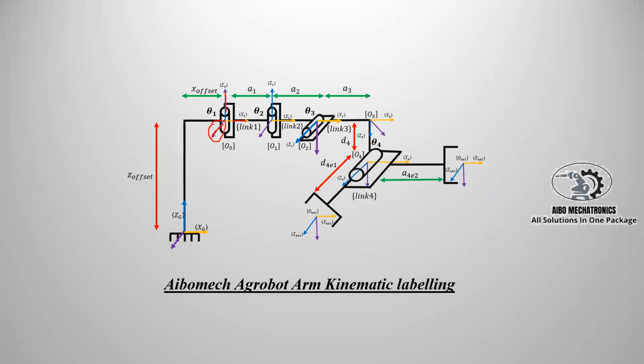Why the Y-axis is not that important. The most important are X and Z, and Denavit-Hartenberg is carried on them. For this one, I suppose it to be an offset, because we don't have any revolute joint or prismatic joint. I suppose them to be fixed parameters, so I take it into consideration as an offset. I will add it after I do my kinematic analysis.